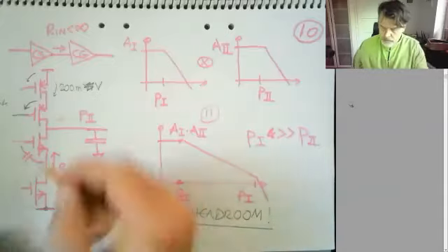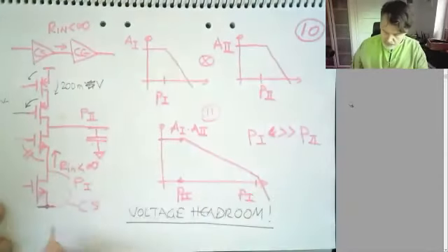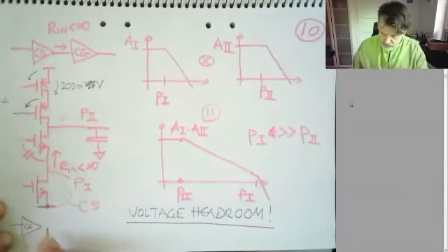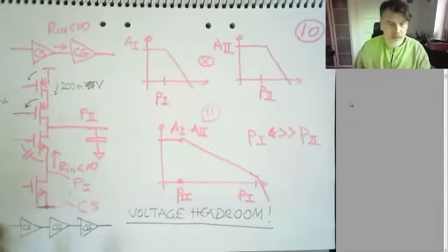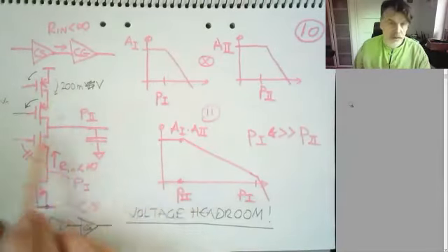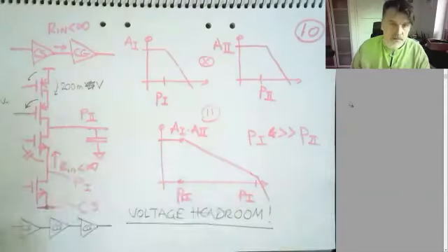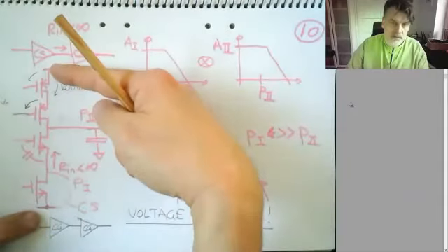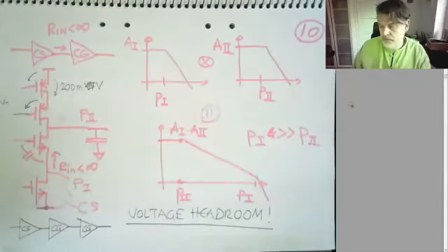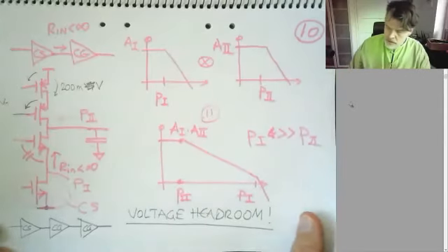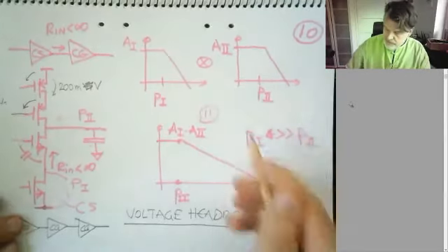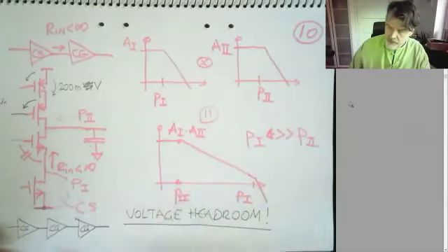For example, I could stack 6 transistors on top of each other, which would essentially be a common source to common gate to common gate. That would give me really high gain, but it would eat up the voltage range even more. And in a modern process, we have only access to maybe 1 volt. And it's quite obvious that this is probably like the maximum you can actually obtain for transistors, to be honest. It is inherently faster, or inherently easier to compensate or bring into the feedback loop, but it's up to voltage headroom.